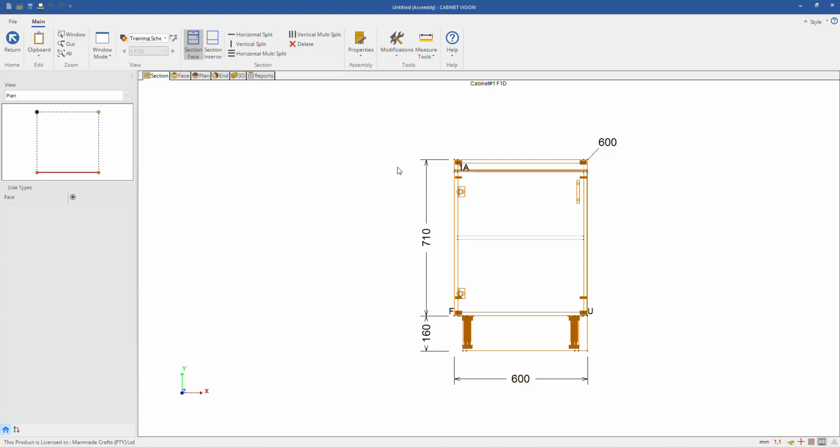It's muscle memory, it's practice. That's why I say rather take 2-3 hours. Go and play around with it. Go and create a layer schedule, call it test, delete or practice. And go and press buttons and see what happens. Hide this, hide that, put that on, and see what it does on your design. Just get a feel for how that works on your different viewports.